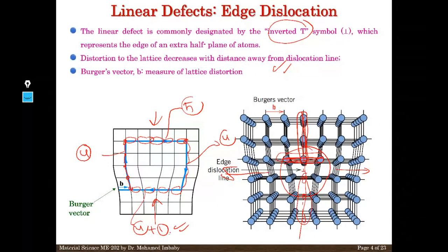Okay, this one, if you need to add 1 here, we added something called a Burgers vector to make balance between this arrangement. This is called the Burgers vector. If the Burgers vector is found, this means this dislocation is there. Okay, dislocation, missing lines of atoms is here. As you've seen it here, it is very clear: an inverted T. Okay, is that clear?